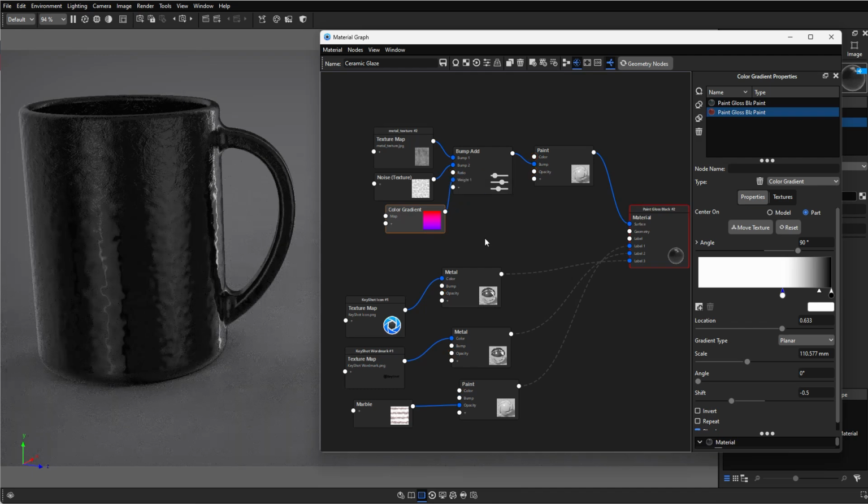What that's doing is affecting the bump height of that metal texture. Anywhere there was the black value, that is equal to 0, so the bump height is 0, or times 0 I should say. And anywhere it was white, it is 1, so the weight multiplier is set to 1, so it's 1 times whatever value of bump height it was. You've then got that gradient between the grey section.